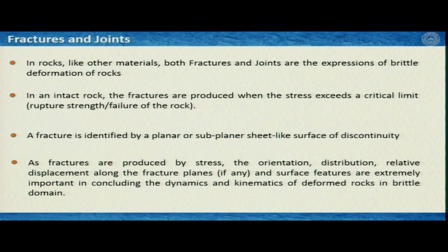So, let us start with the concepts of what fractures and joints are. Now, in rocks, like all other materials, both fractures and joints are essentially expressions of brittle deformation. In an intact rock, you can produce a fracture when the stress exceeds a critical limit, and we generally call the critical limit the rupture strength, fracture strength or failure of the rock.